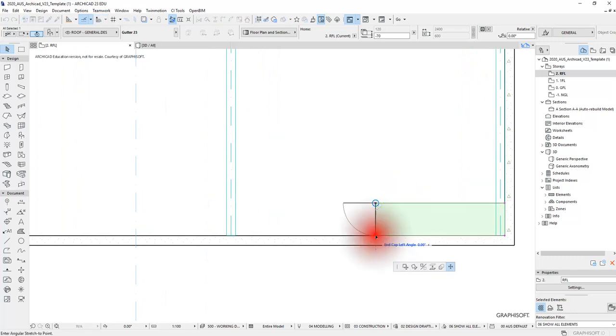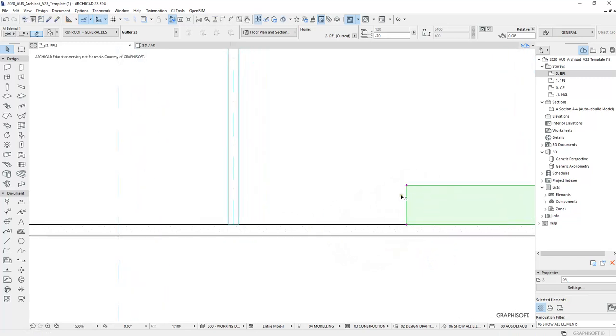Now if I click on this one here, and in the path palette, if I choose move node, it allows me to change the corner angle to 240 degree or 45 degree or 90 degree or whatever that is. So depending on what you want.